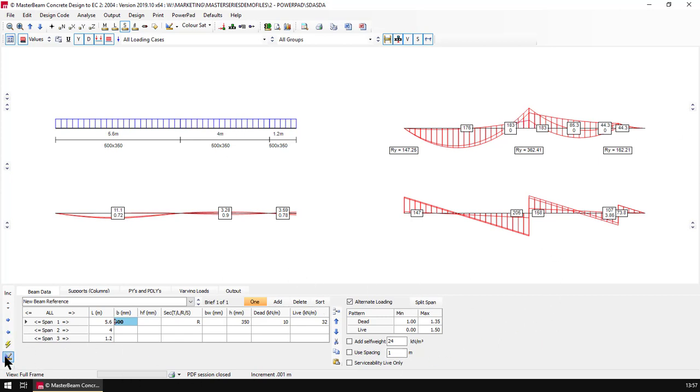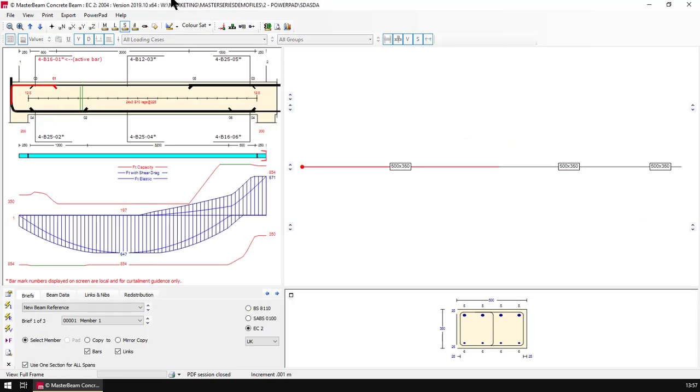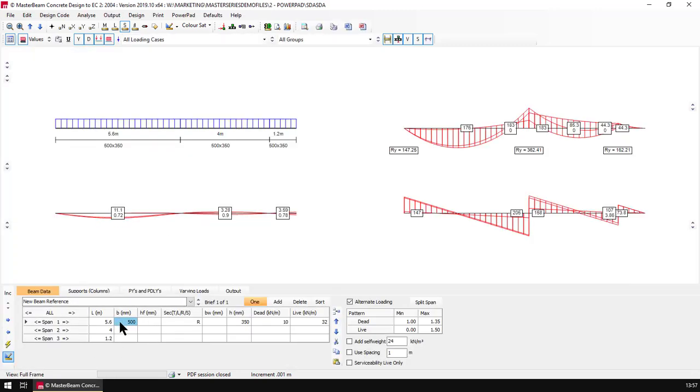And we can then just go in and design our concrete. I'm just going to say OK, and here we go with our reinforcement 425s. It was 500 wide with 350 deep. We were keeping it quite narrow. It's a wee bit unhappy about this bar being unrestrained. In essence, I might actually just nip back and make that breadth into 400 by 350 deep.